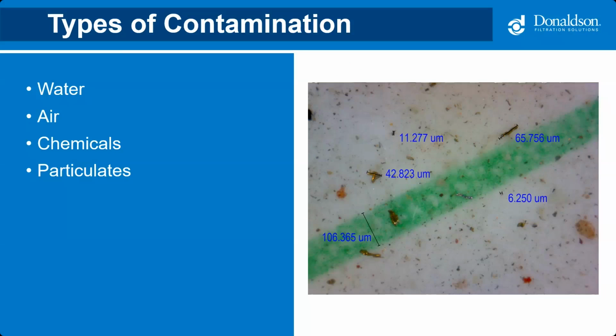Air will do something very similar to water when it comes to being compressed. Air compresses much easier, so you might get soft or spongy. But you also can potentially cause cavitation in the pump, which can start to wear out that pump. Those little air bubbles that are all mixed within a fluid can collapse during that suction, the pressure cycle, and you'll end up with what almost looks like sandblasting on the edges of fins of pumps and tightly machined surfaces. Going back to water too, you can also cause corrosion issues within that circuit and have all sorts of different issues with water.